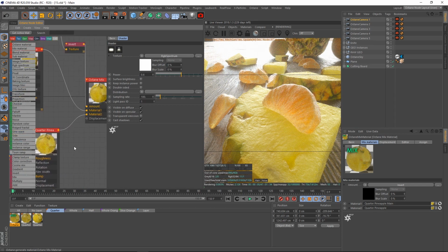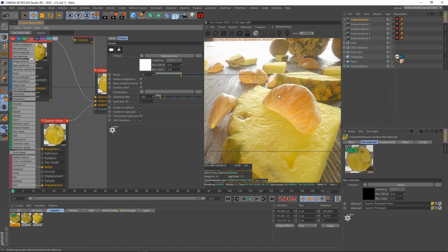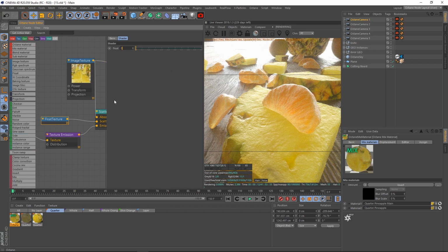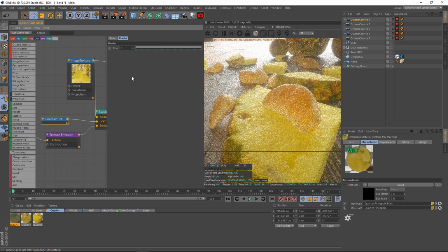And again, that's why we wanted the specular material here with that subsurface scattering going through, and the scattering really helps a lot too, because if I didn't have any scattering here, it doesn't quite hit as well. It just seems too bright, almost like it's not that dense, almost like it's a jello. It's very borderline between a good looking fruit and something that looks like a gummy, so it's really tricky. So I'm going to set our float back to 1, and for me with the scattering at 1, it really cemented in, no, this is not a gummy, this is a piece of fruit. So that's why I really wanted to go with that.